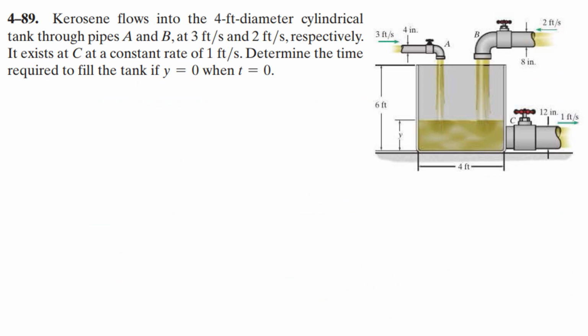So here we have another problem where our extensive property is again mass, but here the mass will change inside the control volume. So our control volume term in the Reynolds transport theorem will not be equated to 0 now. It will be considered in the equation. So let's go through the statement.